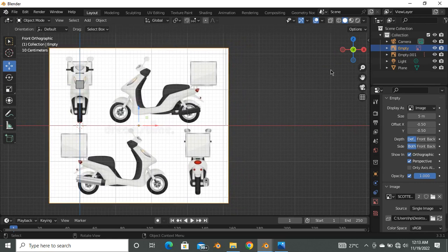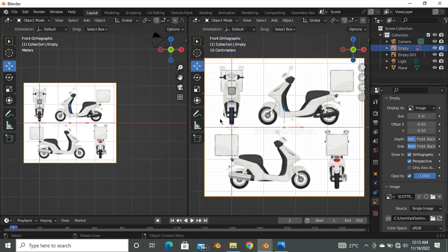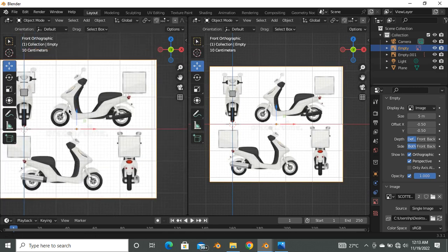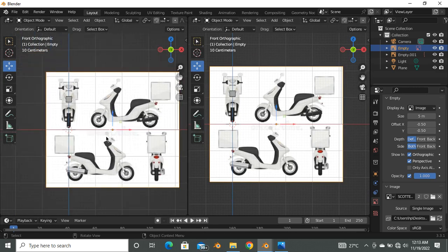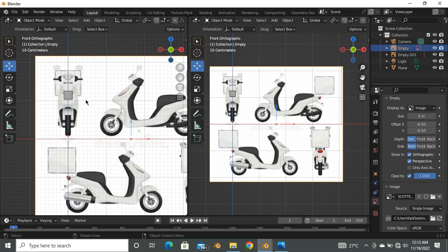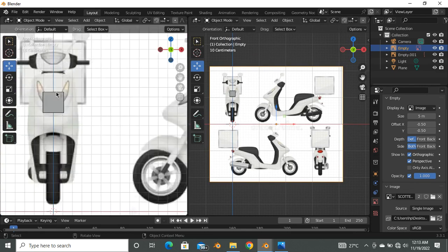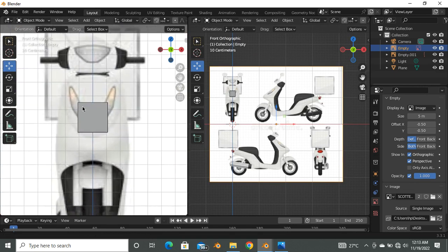So hover your mouse to this point where you have this arrow facing like this. So I can right click on it and say vertical split, and a very faint line comes up. I can bring it to the middle of my screen here, and if I click, now I have two screens. So now anywhere you hover your mouse, that's where you can work on. So I'm going to bring this way. My front view will be this side, and I can change this.